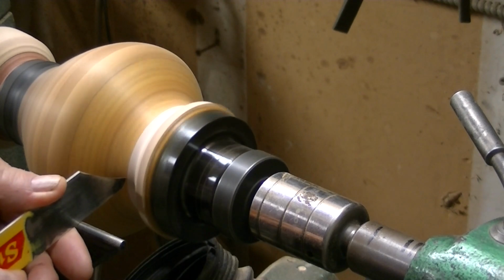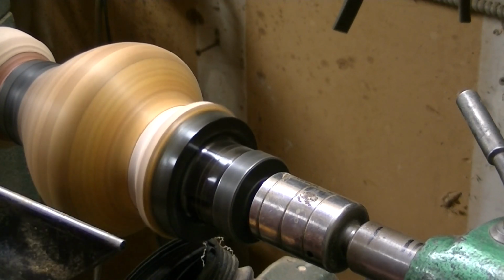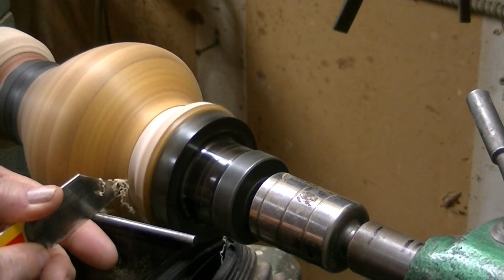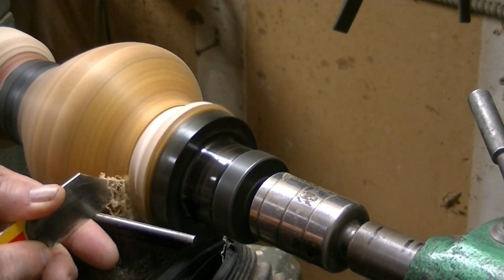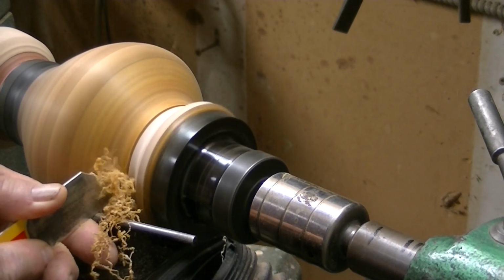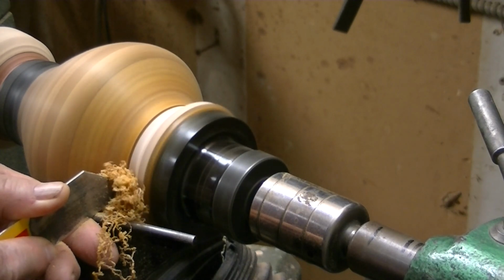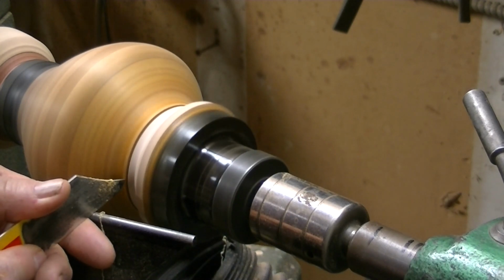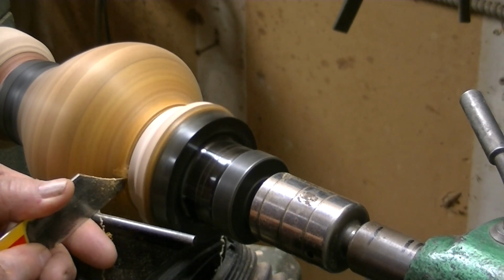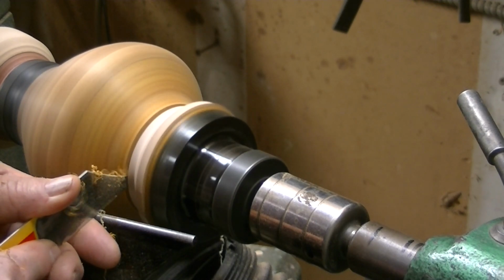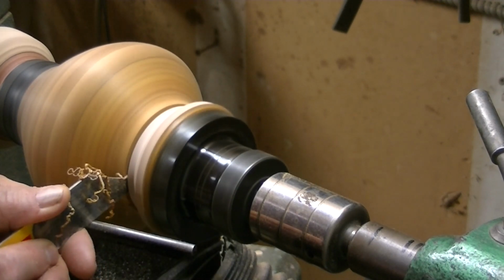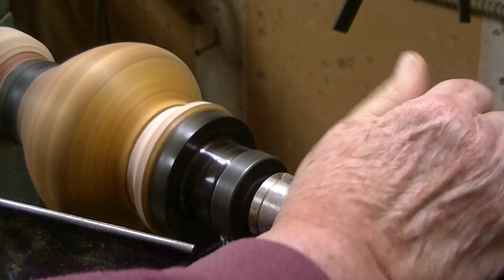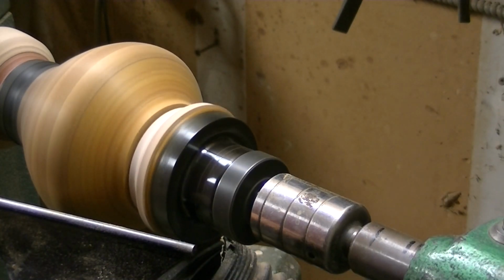So after the glue is dried, there may be a little cleanup on the outside surface. May need a touch of sanding again. But ultimately after that's done, it's time to part off at the neck of the vessel. So I'm using a thin parting tool, specifically one I've made myself, that takes away very little wood. But I still do overlapping cuts. One cut goes in, the next cut goes over about a half of the tool width, so that I never have an opportunity for the tool to get bound into the joint and jerked out of my hand. And after a few cuts, we eventually part off the glue block.